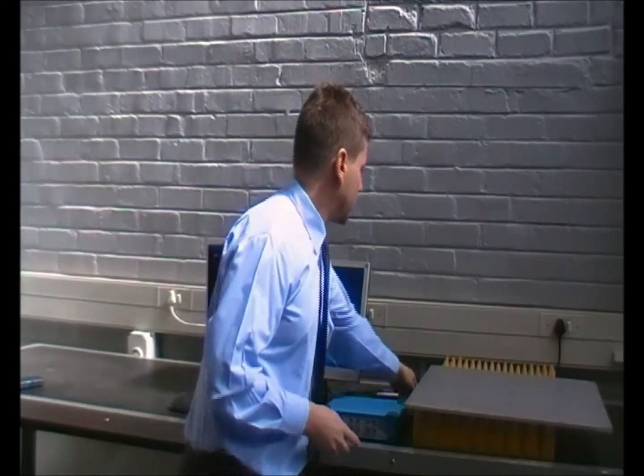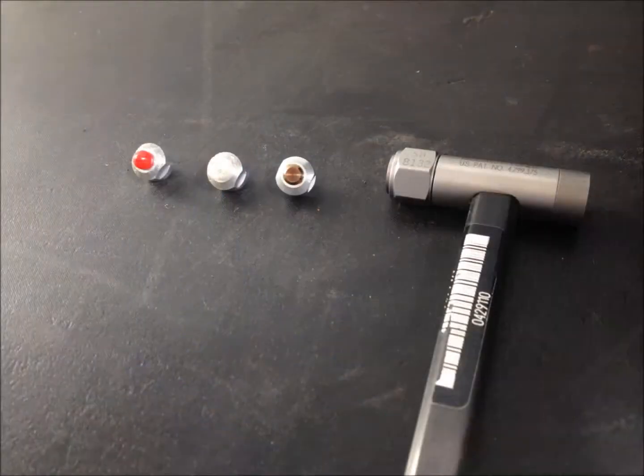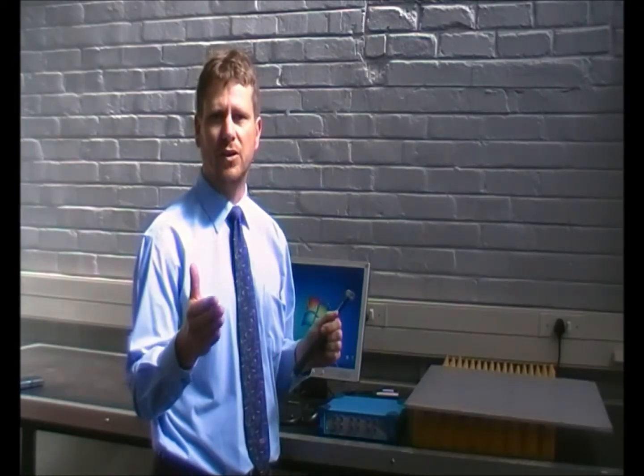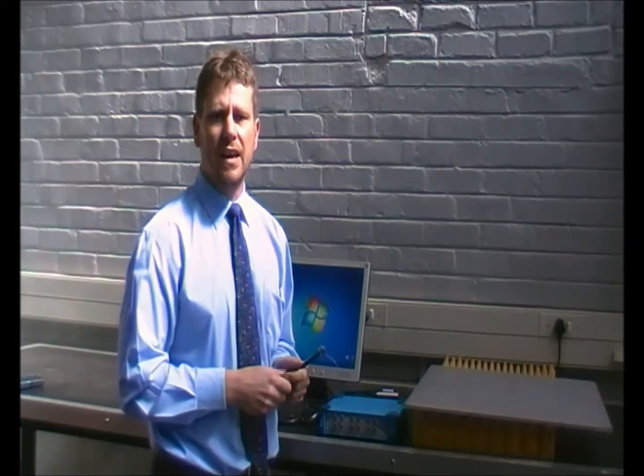We are also going to use a modal hammer, a PCB model. And you will see that you can use interchangeable tips, and there are three tips available. The first tip is a soft rubber tip that you typically will use if you're interested in frequencies up to a couple of 100 Hz, typically 200 Hz.